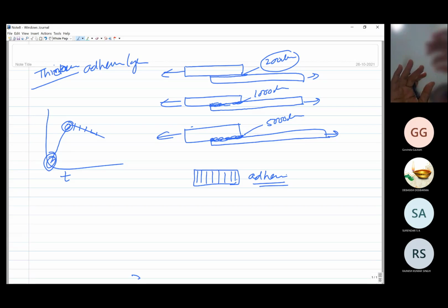When it is thin, you will find that the adhesive on its own has a failure tendency, because it is weak, so it will not fail when it is very thin, and there is a possibility that part of the failure may occur from the adhesive and the metal interface, part of the failure may occur from the adhesive, part of the failure may occur from the base metal side. So there are 3 or 4 possible ways by which these failures occur. Let me talk about that a little bit.